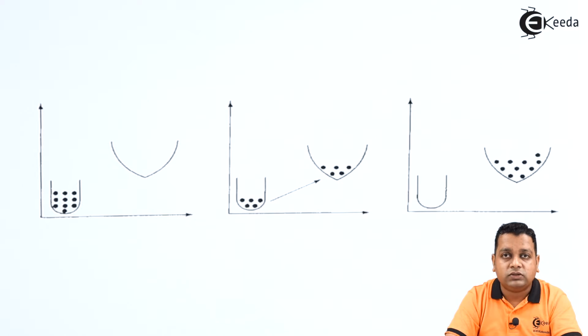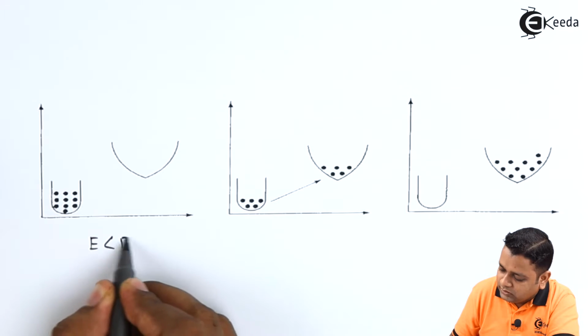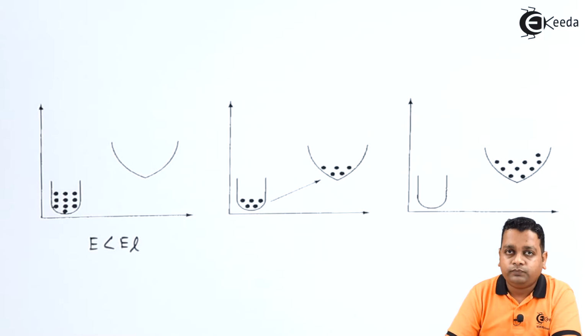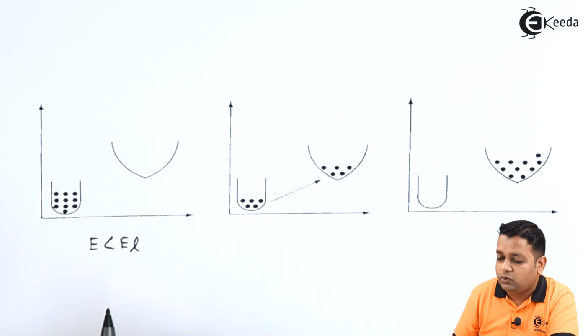So as in the previous case, to see the differential negative resistance, we had the voltage controlled mode and the current controlled mode. There we had the graphs with respect to the increasing electric field, let us say E1 to E2, where we got a drop in the current density from J1 to J2. So to see how exactly the negative resistance occurs according to the two valley model, we have three cases. On the left hand side we have the first case, where capital E is less than EL. Here the suffix L represents the lower valley.